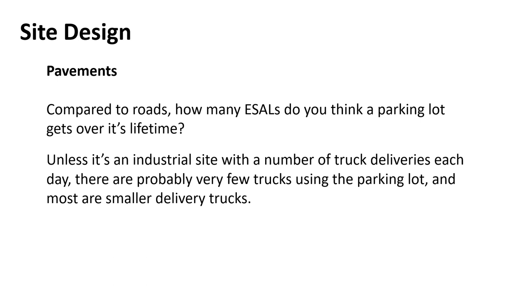If there are any, if it's that big of a medical complex, they usually have a loading area on the back side. So in the front area where the patients will come in and so forth, that's going to be very light residential and just passenger vehicles generally, right? And we've already learned that a truck has 5,000 times as many ESALs as a car does, right? And so you're going to get so few ESALs in a parking lot. That's not usually the issue, right?